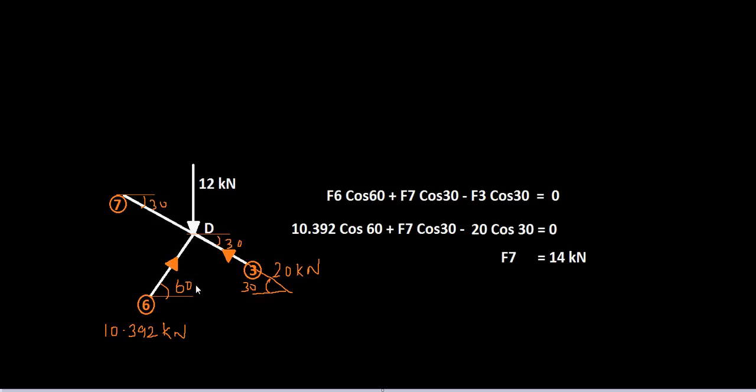You can either apply the horizontal equilibrium or a vertical equilibrium. Let's consider the horizontal equilibrium, because that's the equation I have written here. You have components of force F6, vertical and horizontal, components of force F3, vertical and horizontal, because these are in these directions. You have this one upward and this one in negative x direction, and components of force F7, you don't know the direction yet.